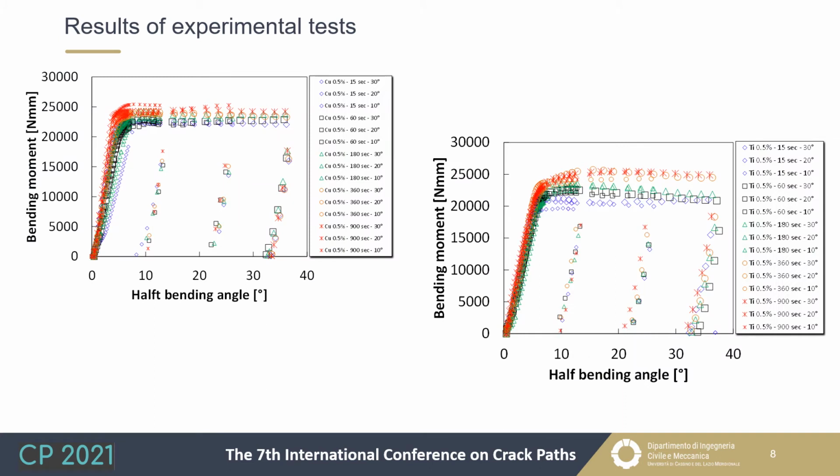In this slide you can see the bending behavior of the zinc copper coating and the zinc titanium coating. You can see that high values of the bending moment are achieved for high values of dipping time. This is due to the bigger values of thickness achieved in both cases, titanium and copper bath. And the main differences are for high values of deformation.